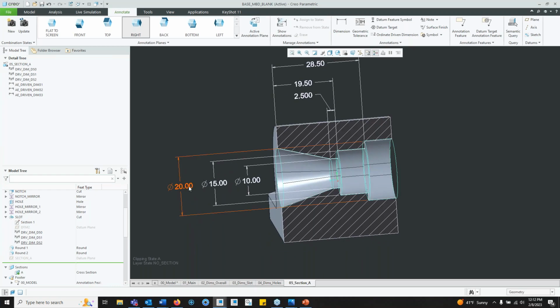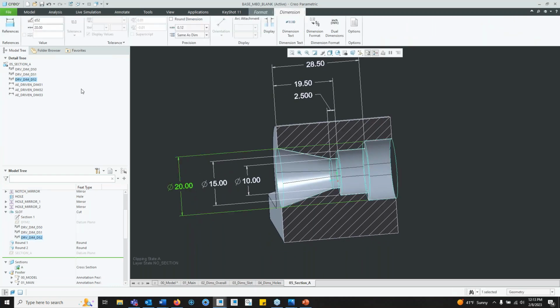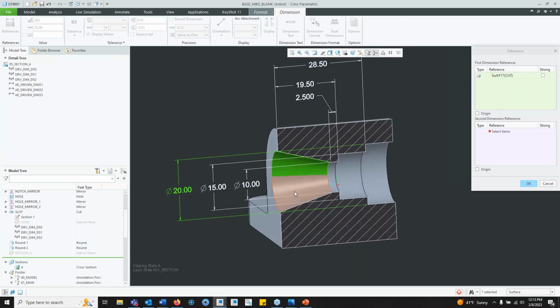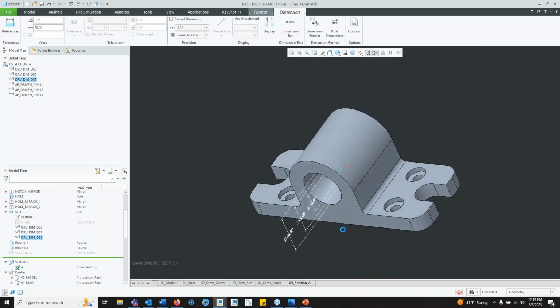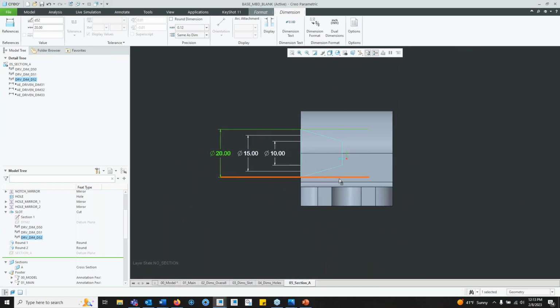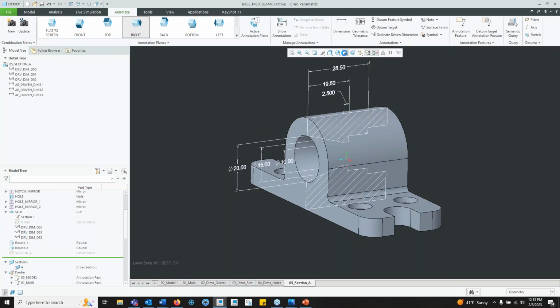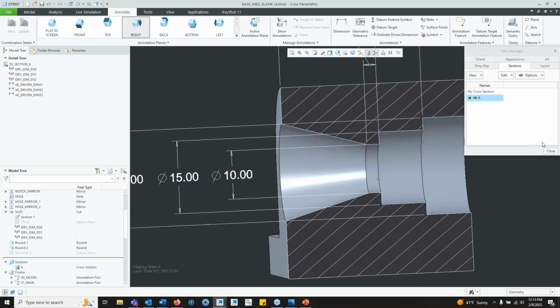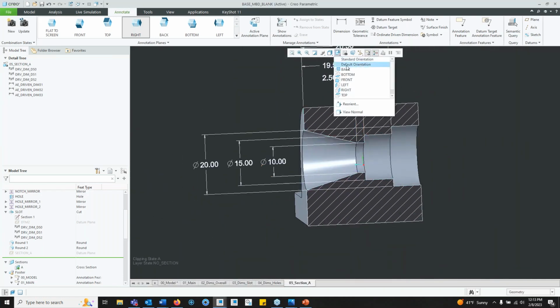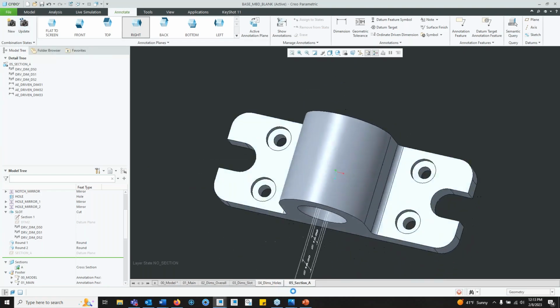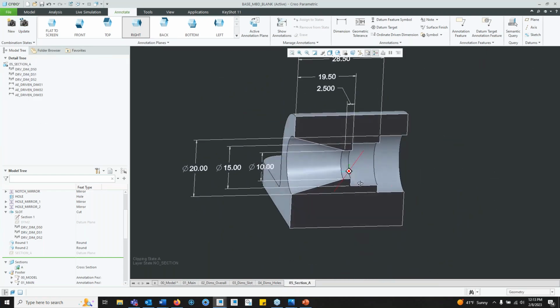With these, I'm going to also change out their references a little bit. So this is different. This references tab becomes available here, and then I'm able to select new references. Like that. And then I could also choose right side, show section, activate, cut out of there. You can see I'm going into right view here. I'm gonna hit update, so it saves this combination state so far. So update, and now when I switch between the two, you'll see that it'll automatically turn on the section.